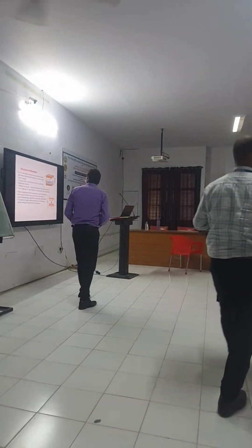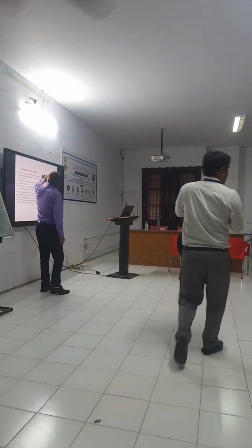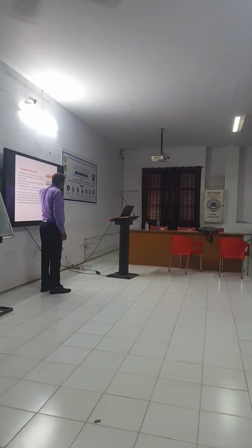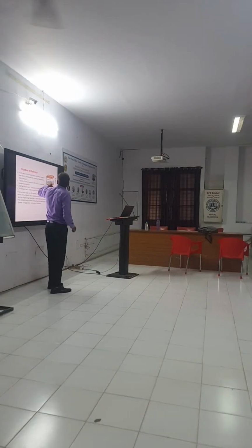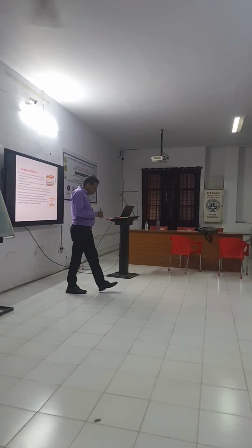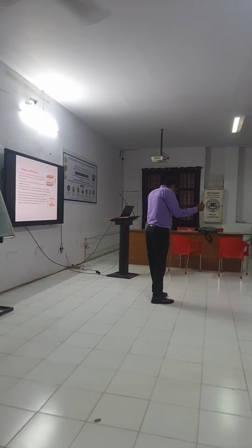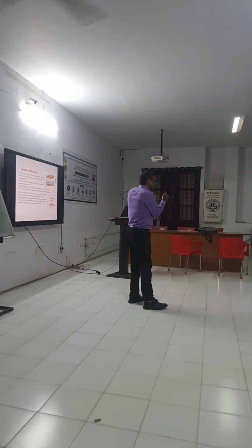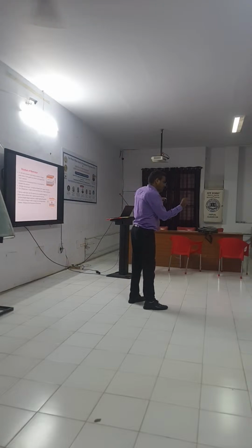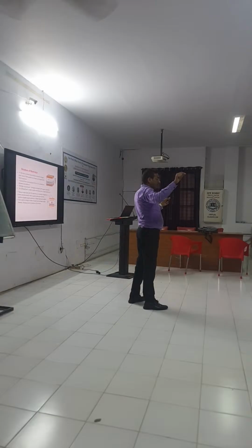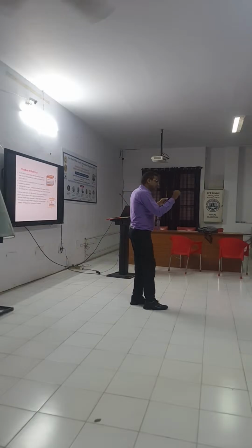Basically, this is the structure of the memristor. You can see the top electrode and the bottom electrode, the anode and cathode. There are two layers, one doped layer and one undoped layer, with titanium oxide material inside. When you apply a potential, the oxygen vacancies shift towards the other electrode. If oxygen vacancies increase, that means less resistance and increasing conductivity.